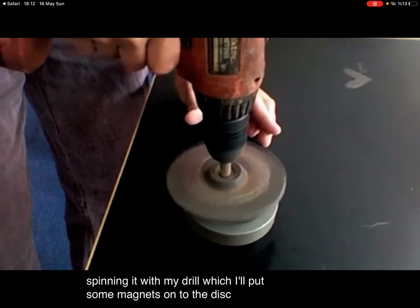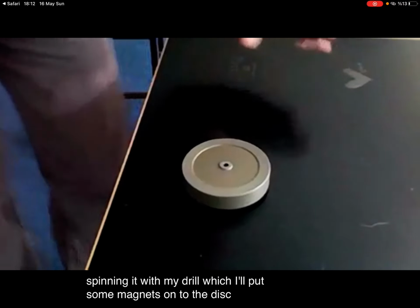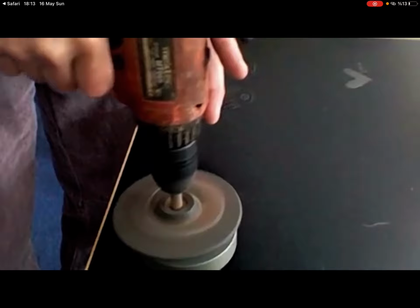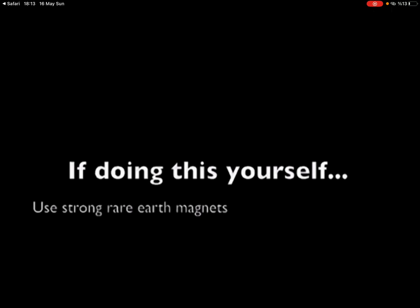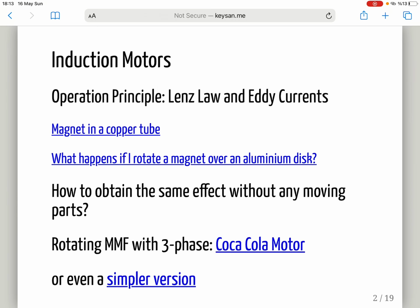Again, I would like to emphasize there is no attraction between the aluminum and magnet, so it's not rotating by attraction, but it is rotating due to induced currents, electric currents in the aluminum, and those induced electric currents are interfering with the magnetic field. We have seen it with the synchronous machines in the first weeks. We were applying a rotating MMF with 3-phase, and with the help of that rotating MMF, I will be able to generate some rotation.